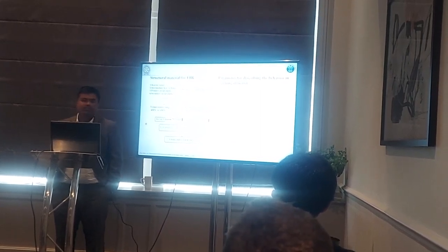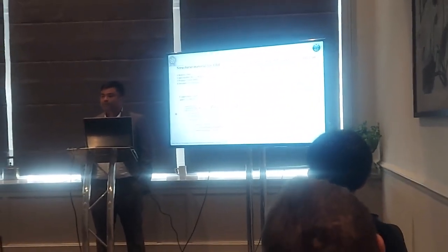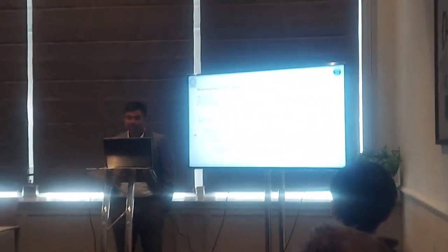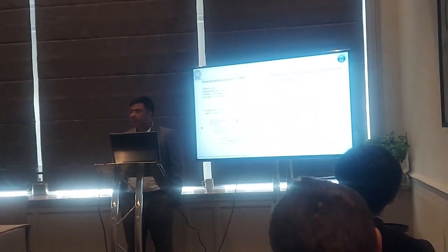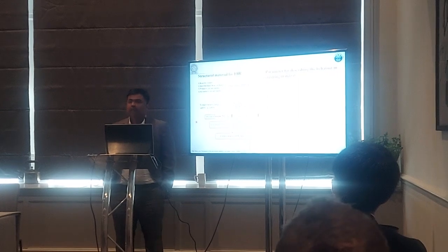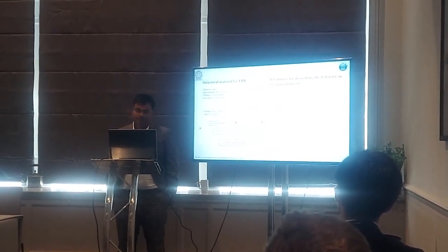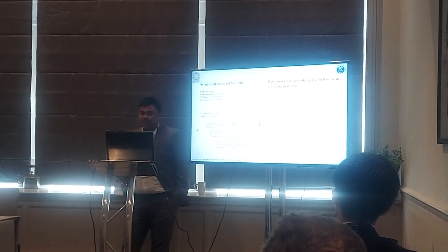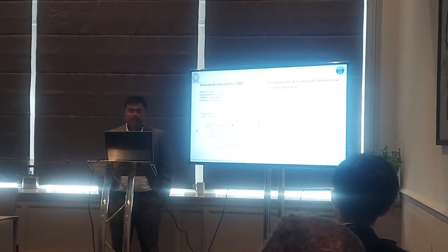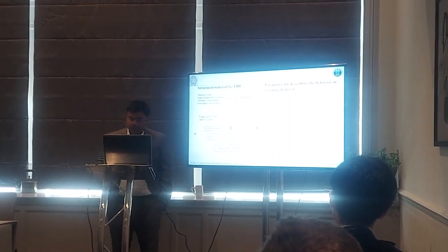So we cannot use LEFM and EPFM parameters. We have only the time dependent deformation parameters, which are used for characterizing the crack in these conditions. Other parameters have been worked out depending on the magnitude of the creep zone in the material.